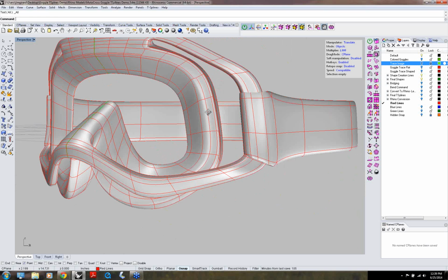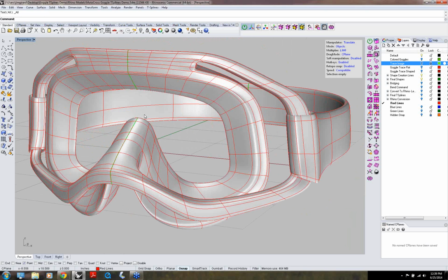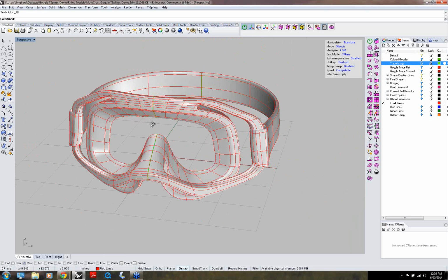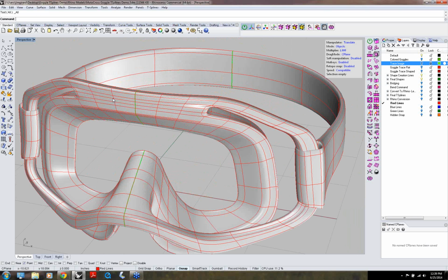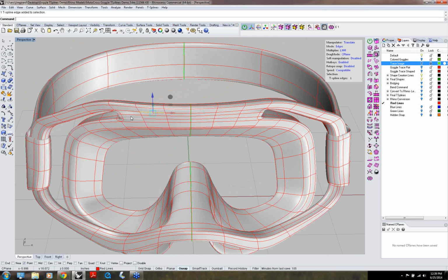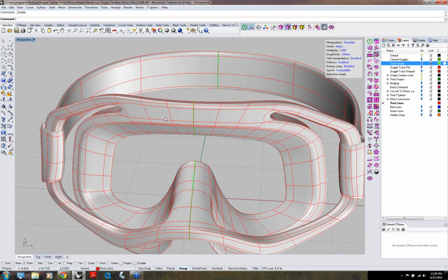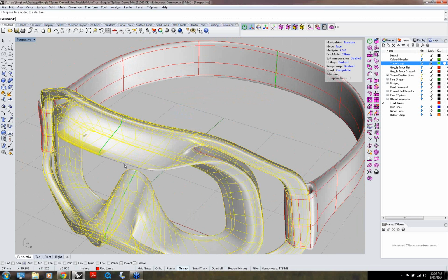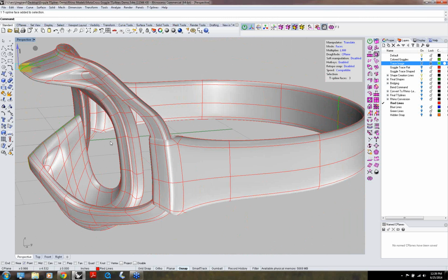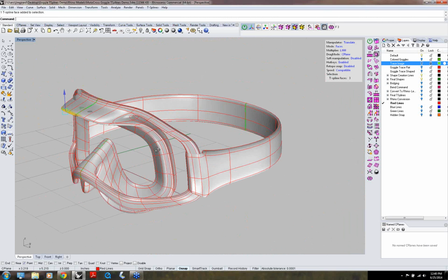And again, there's the model. Now when you get to this level, you start saying, well, I could have done this in Rhino, but the nice thing is you can start saying, well, I wonder what happens if I get these here and these here, and we'll loop it and delete those. And now what happens if we come out here with a brim for this thing, for a concept? So you pick D and you pick those edges, and now you just pull it out. Now you can start, again, designing. You can take your base model and then go from there to do maybe 4 or 5 concepts, because it's basically virtual clay.